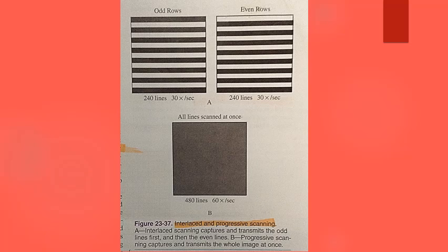HDTV picture quality. The most impressive attribute of HDTV is the picture's visual quality. To compare the HDTV image to the analog image, we must first convert the typical analog image to an equal digital resolution. The National Television Standards Committee, or NTSC, formulated the standards for analog television and video in the United States. The NTSC standards call for 525 scan lines at a 60 Hz refresh rate using the interlace technique.